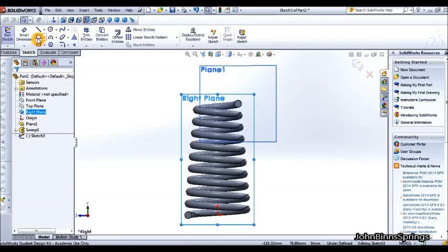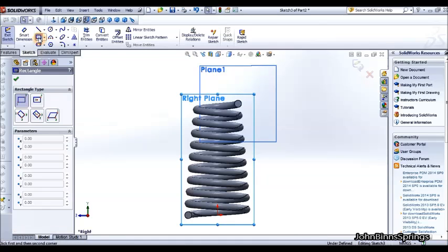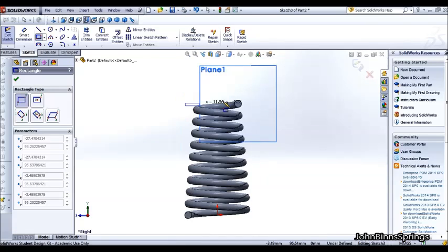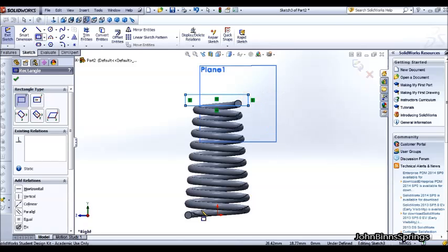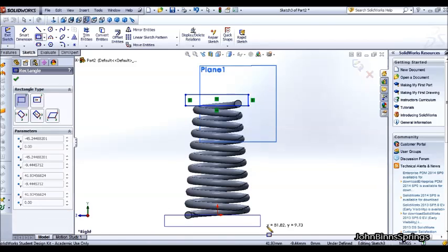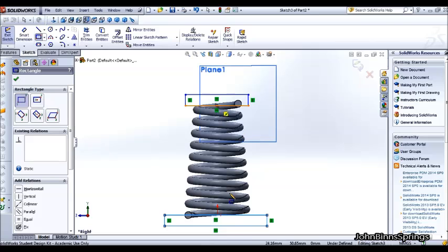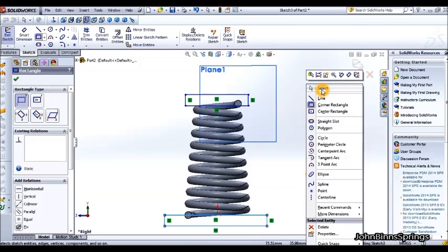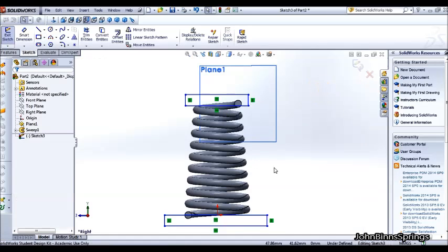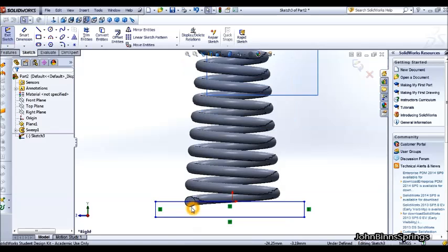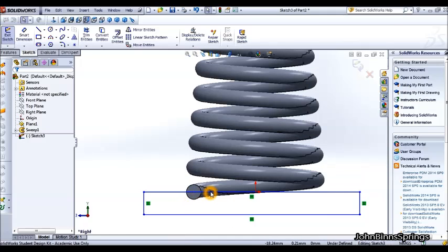And the best way of quickly cutting a bit off the top is to use the corner rectangular tool by clicking up here and just drawing a rectangle up there and one down here. If we do both at the same time, it's twice as fast. So then you want to select out of there. The next point is to give that a measurement from this line here to the bottom of the surface, so you know how much is going to be grinded off.